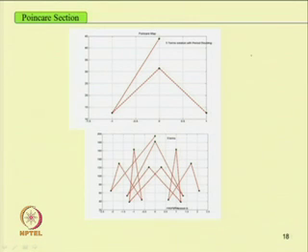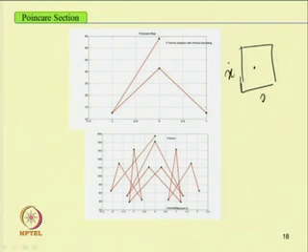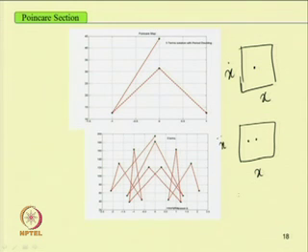In the case of a periodic system, if one plots x dot versus x, we will have a single point. Corresponding to two periods, we will have two dots, and in the case of the chaotic response, if we plot the Poincare section, then it may fill up the space.